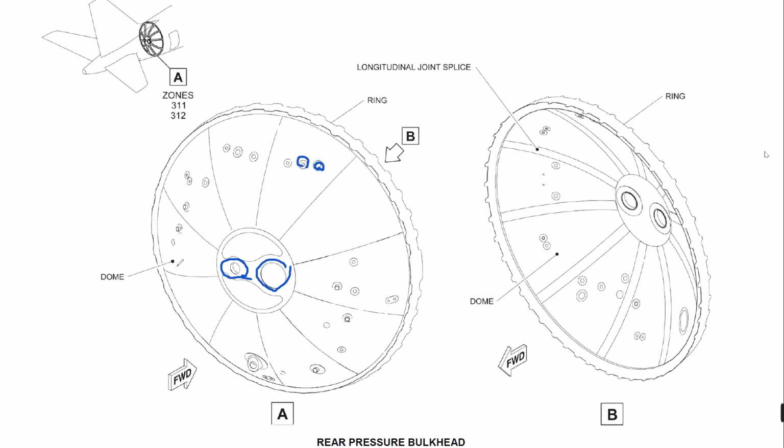So there are some, as I said, hydraulic lines or electrical wiring, but not only electrical, but also different harnesses, which are also fuel we have, which is for the APU. And we have some specifics in these openings. We have specific pressure seals, which are keeping, of course, this cabin pressurized. So this is the ring and the joint splice here. Joint splices between the different plates here.